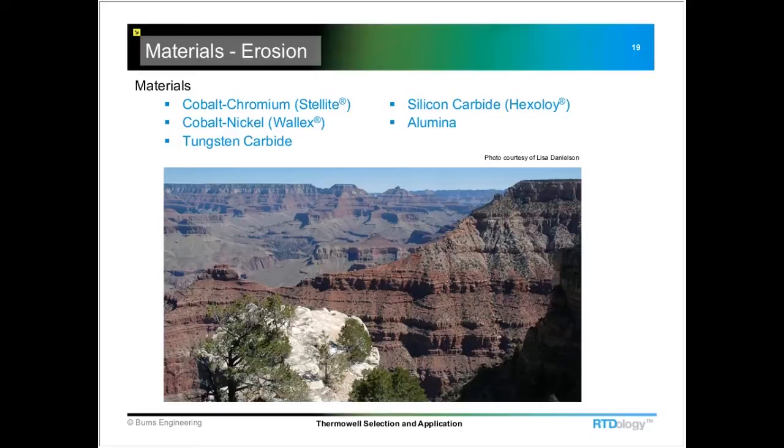I had one instance where a manufacturer of granules for roofing shingles had called in and had a Thermowell that had been completely eaten away by those little gravel particles that you see on housing shingles, and it actually eroded away the whole Thermowell and also part of the thermocouple that was inside the well. And curiously enough, the thermocouple was still giving a temperature reading.